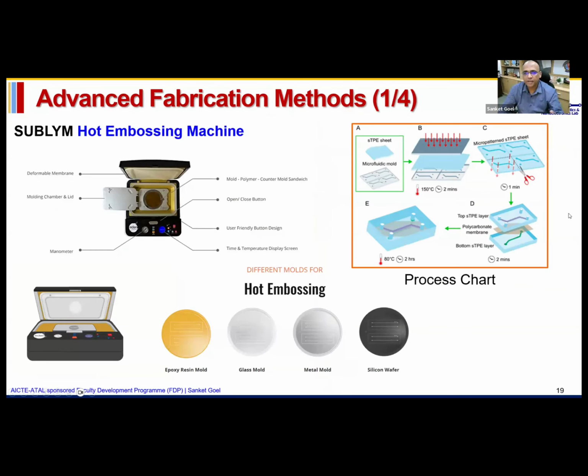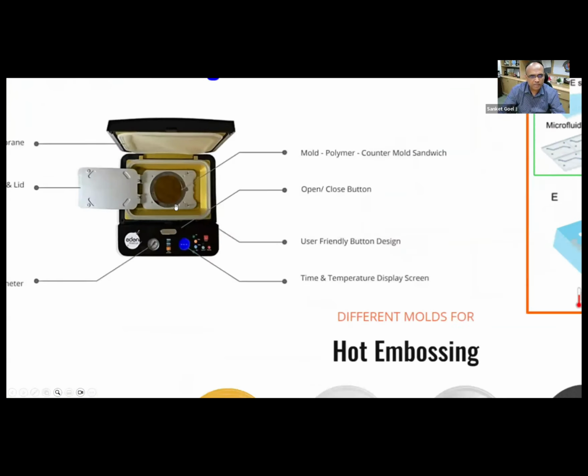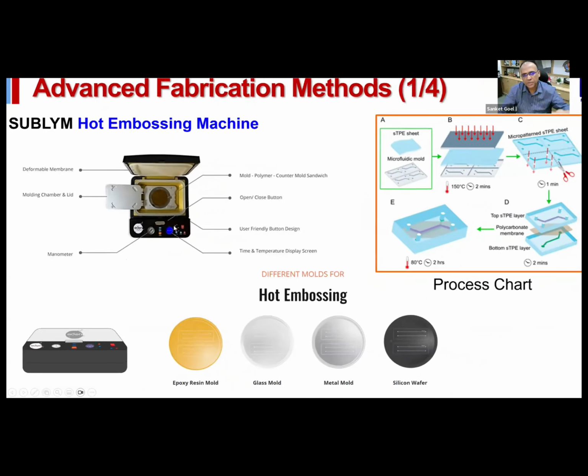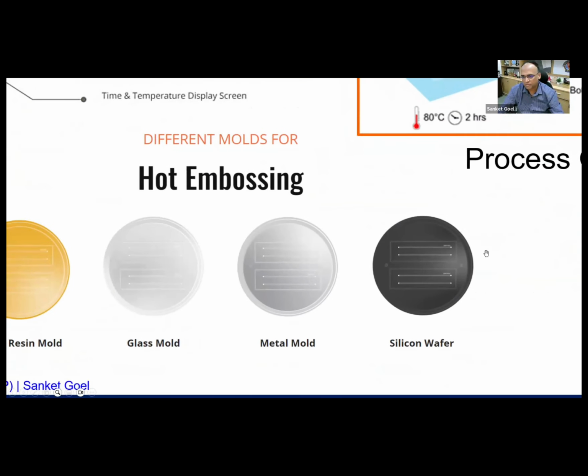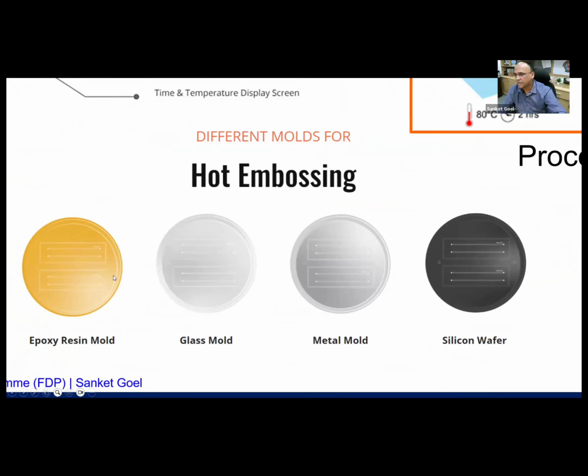So far, we have tried to understand what microfluidics is and what the different components of microfluidics are. One of the first components is how we fabricate the microfluidic device. In order to do that, I have shared two major technologies. Number one is photolithography with the mask, and I also shared maskless lithography with the software mask. The other method is hot embossing. We can create a mask here, and then using temperature and pressure, you can create the replica. So basically, this is my master on the left, this is my slave. And with one master, you can create multiple slaves, multiple devices.